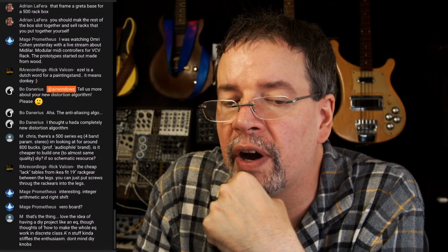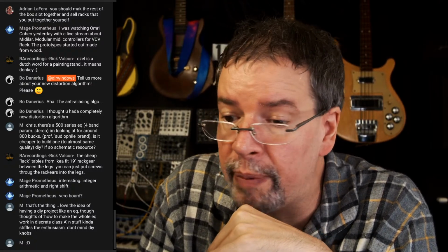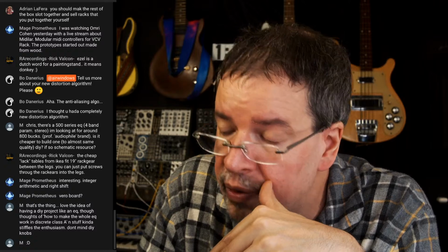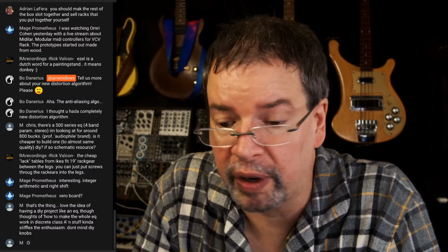The other part is the non-passive parts, and that has also interesting discoveries. For instance, you can get op amplifiers that are 39 cents or so. You can also spend like $3 for an op amplifier that's much higher performance. I've got a collection of op amplifiers of different kinds. Some of them I chose because you can restrict them and make them kind of your grungy old school op amps. Some of them I got because I knew that they were high quality. For instance, Analog Devices make a bunch of op amps that are good quality.